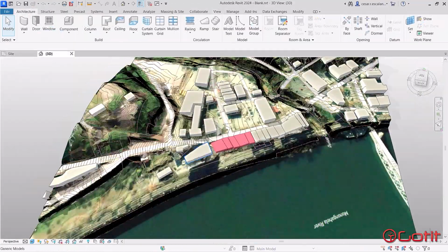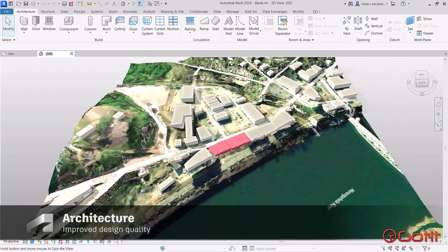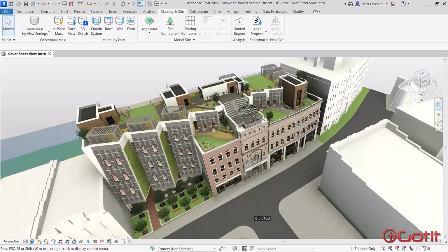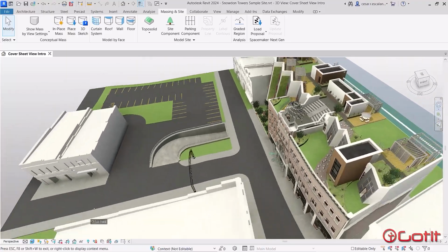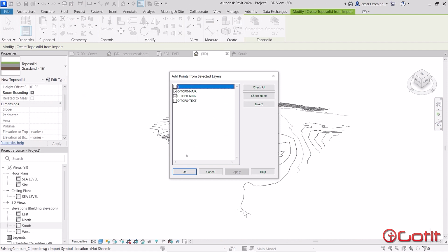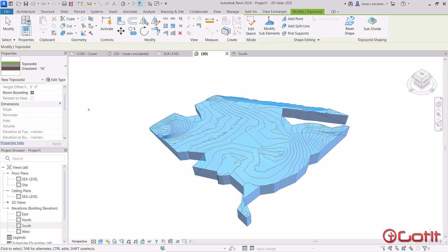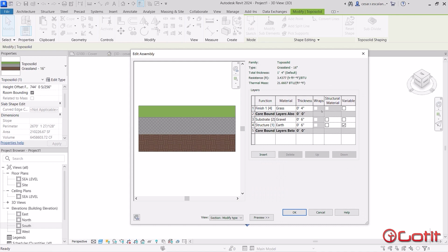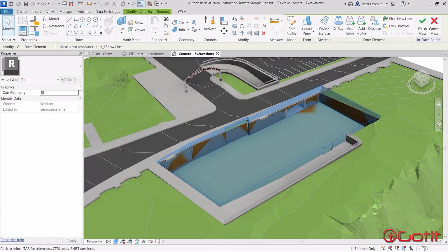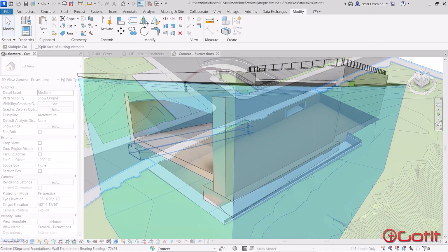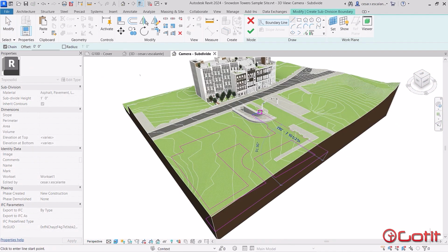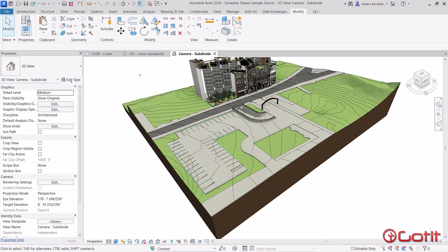Revit 2024 helps you improve the quality of your site design with the introduction of toposolids. Model topography and document landscape projects more efficiently. Toposolids are families built from CAD imports as solid geometries with complex compound layers and tight parameters. Model site excavations or tunnels using solid Boolean operations with mass voids. Cut topography with elements in other categories. And make faster edits with split and subdivide operations.